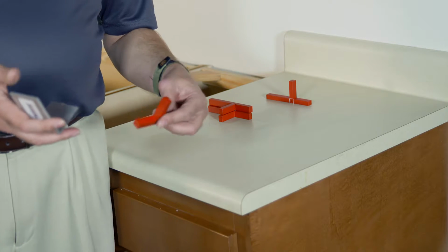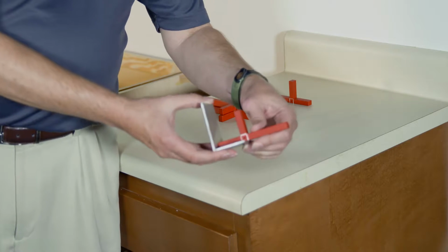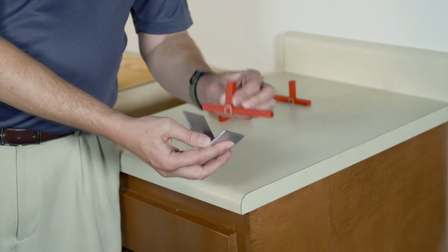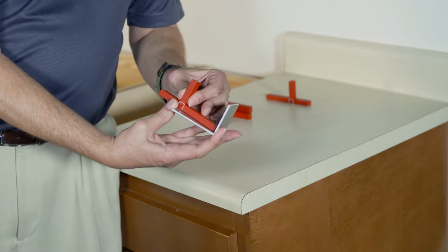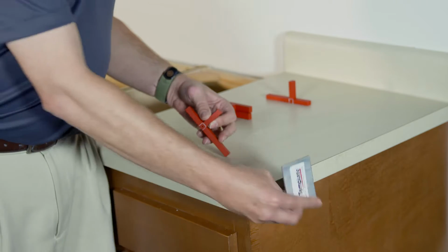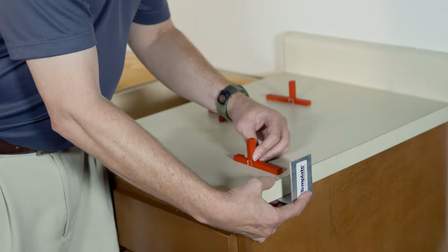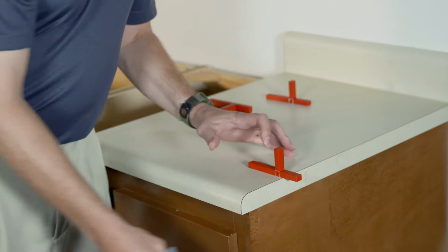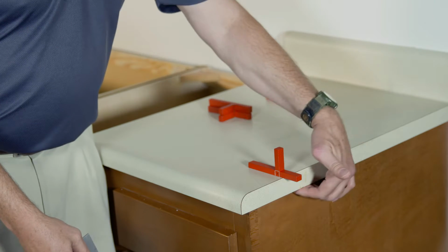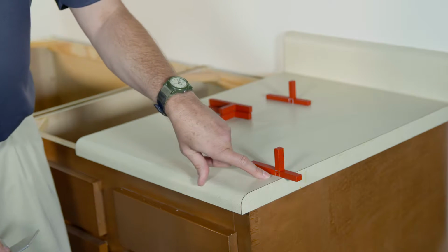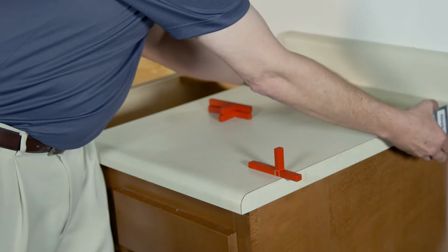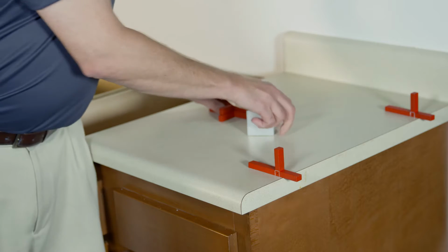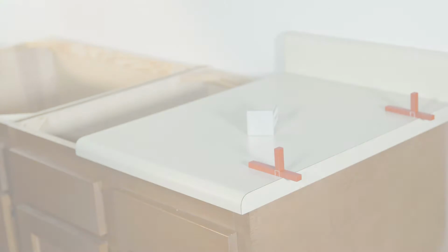By combining with this L bracket, you can see that the short length of the T is the same as the short leg of the L, and the long leg of the T is the same as the long leg of the L. So what we do is we place the L bracket underneath the top and just snug the T bracket up against it. Now this back edge of the T is right in line with this, as well as a scribe line on the side. I'll just do this in two positions with this edge, and we're ready to measure, and we'll just go over and work on the other side.